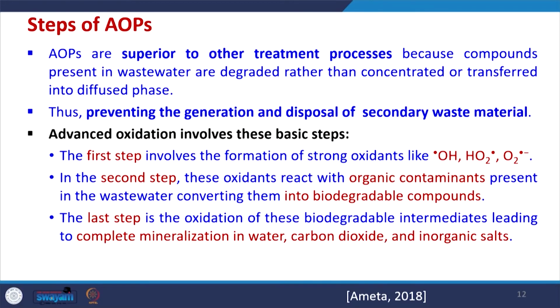So, there are still many challenges with respect to their utilization for industrial wastewater treatment or otherwise. Now, what are the different steps involved in the AOP method of treatment? AOPs are superior to other treatment techniques because here the compounds are degraded rather than concentrated. We are totally removing the compound itself, degrading it, not separating it out or concentrating it or transferring it into a different phase. So, we do not have any secondary waste being generated.